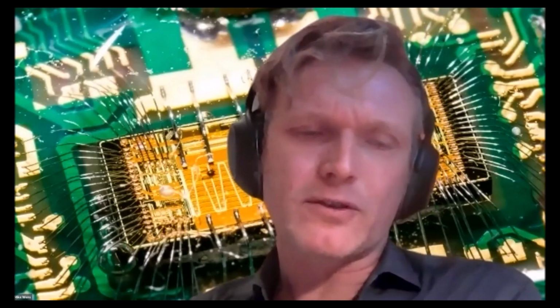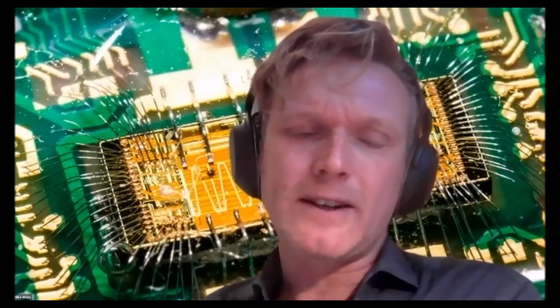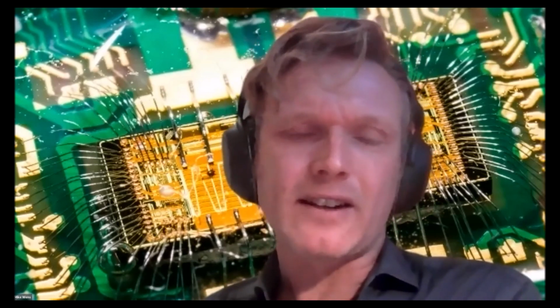At these high frequencies, you basically build an FM radio station, and not many applications may actually like that. So that's something to look into. If I look at my customers for these point of load converters, EMI is really a key thing, because you may have many on a system, on a board, and they all are radiating like hell, and that somehow needs to be kept within limits. So EMI is definitely an issue.